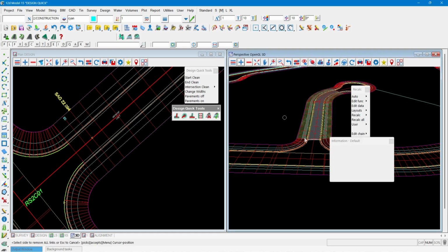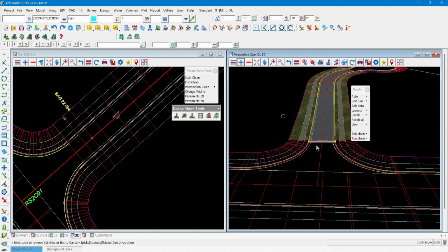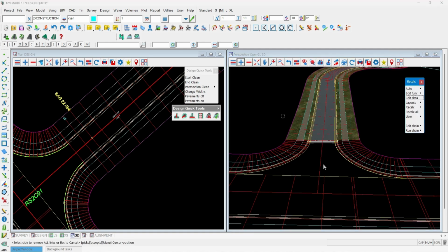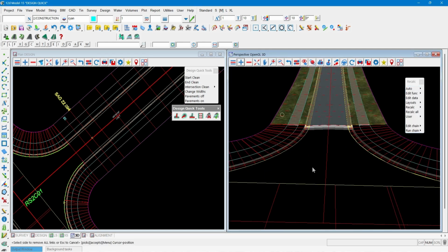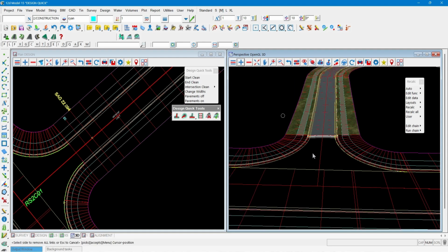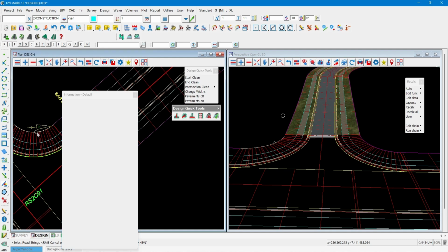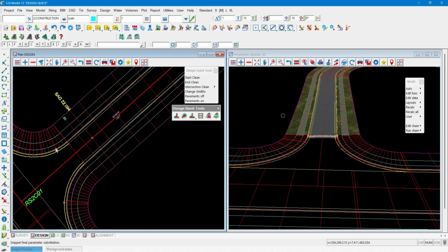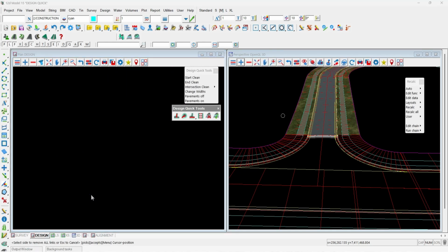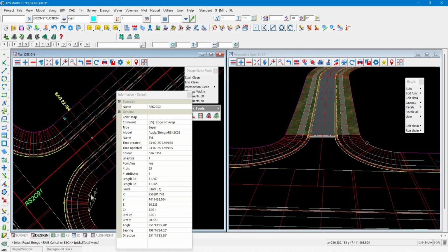I can zoom on in, and you can see that that's turned on all of the snippets that have been using the Pavement Styles Manager or the Pavement Manager New. And then we'll have a look at the Pavement Manager in a little bit more detail in a minute. But subsequently, I'm going to add the tri-mesh pavements on for all of the rest of my intersections, so these curve returns. And you do have to repeat this command at the moment because you typically wouldn't be doing this over and over again.